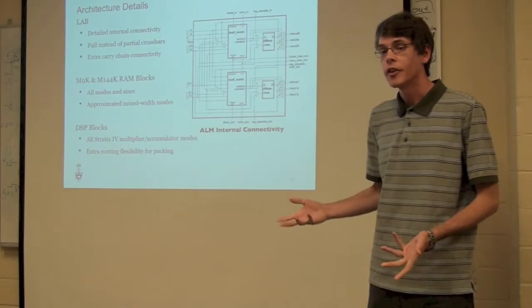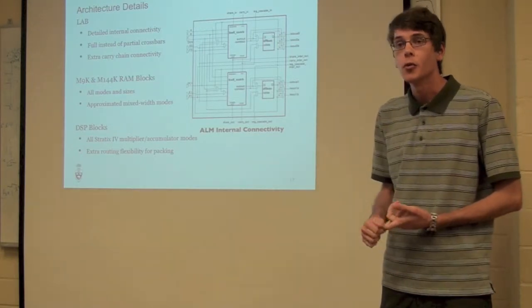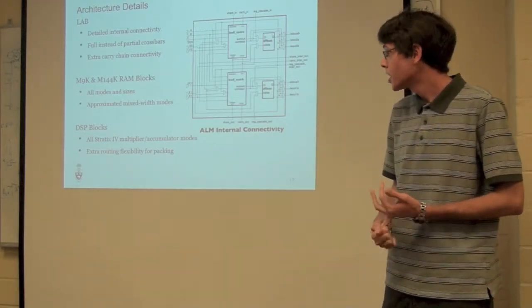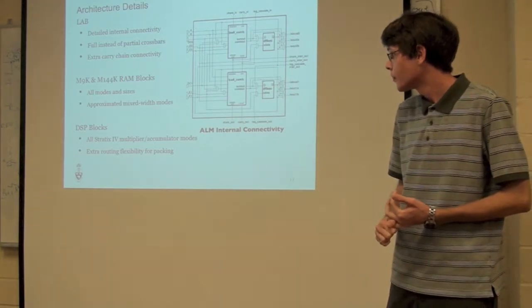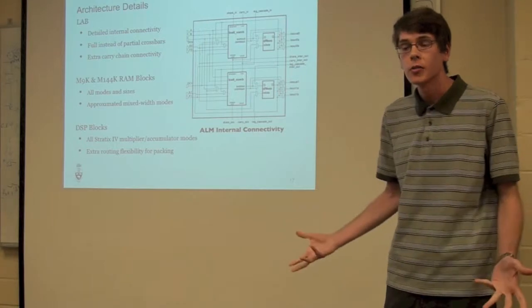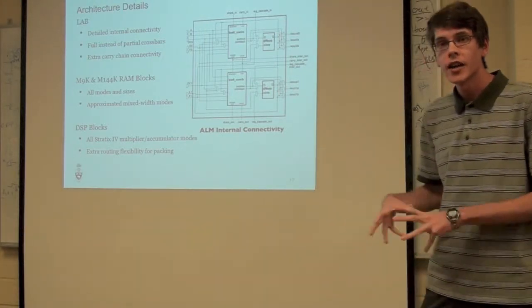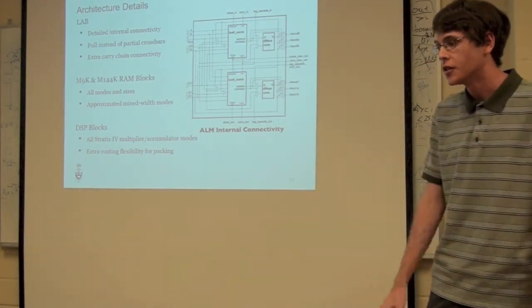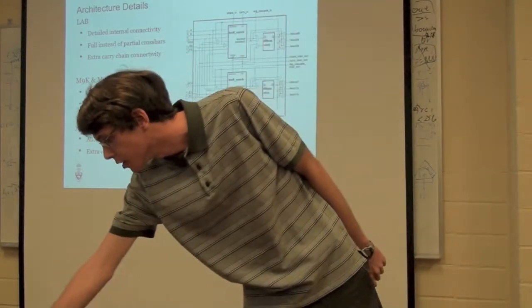For the two types of RAM blocks, we support all of the operating modes and sizes, although we did make some approximations to mixed switch modes. For the DSP blocks, we support all of the Stratix 4 multiplier and accumulator modes, although again, we had to add some extra routing flexibility so that the design would pack successfully in VPR.